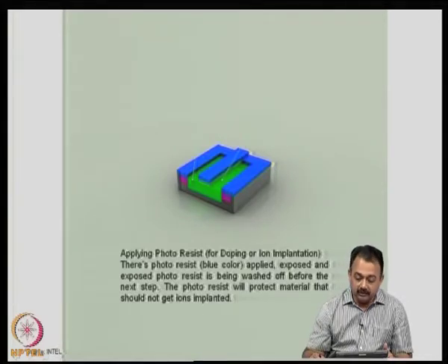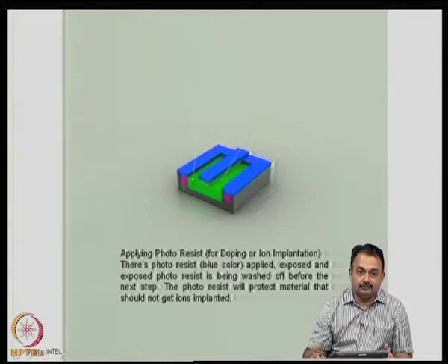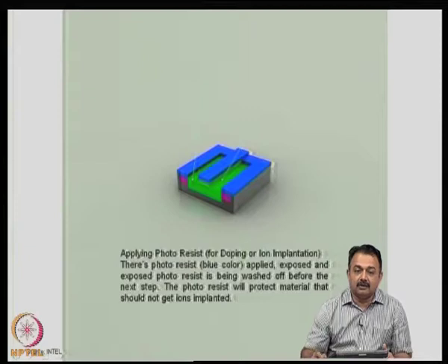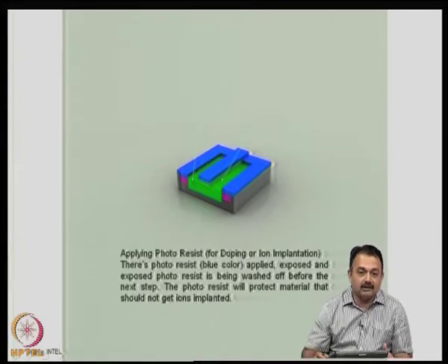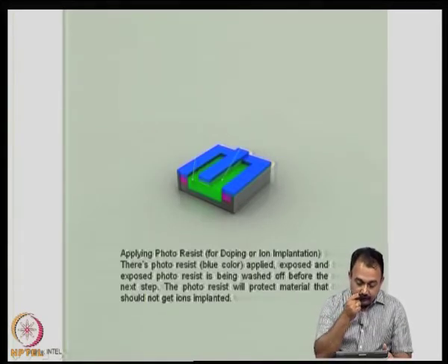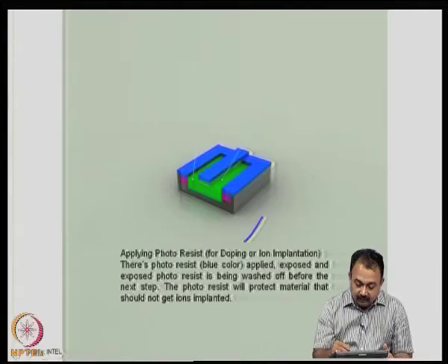These are some of the dopants. They are used to change the property of the semiconductor to improve the electron mobility, and therefore, the next step will be in those areas where the transistors are going to be defined, you are going to do some kind of doping. So, you have to predetermine what dopant you are going to use.